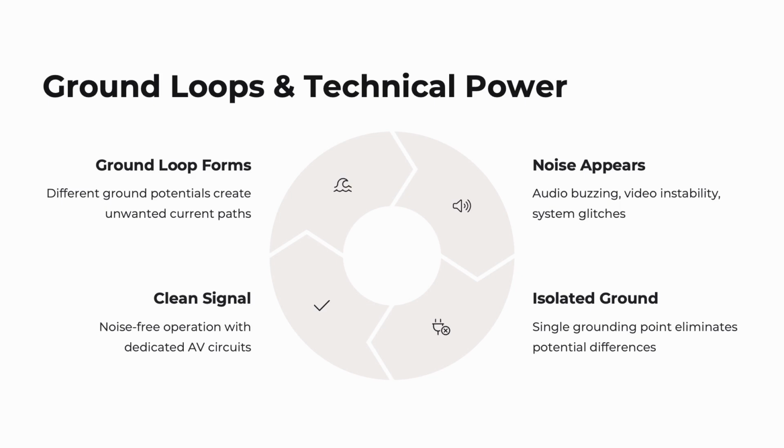Many AV systems use a technical power setup or a dedicated isolated ground electrical supply used only for AV and IT equipment. This reduces interference from high noise devices like vacuum cleaners, power tools, coffee makers, and fluorescent lights. When you're out in the field, mark these outlets clearly, and when possible, use color-coded faceplates to avoid these mistakes.